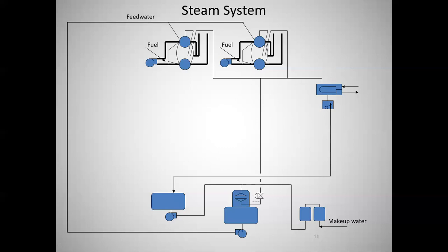Like in the Tech mechanical rooms, they've got these little package condensate receiver stations that have pumps on them. And so, you know, we're pumping steam into the building. We make hot water in the building. The steam condenses, falls into that little receiver down there. It's got a pump on it, and it pumps it back into the condensate return line, which pushes it back to the boiler house. Because Tech wants that condensate back too. Okay.